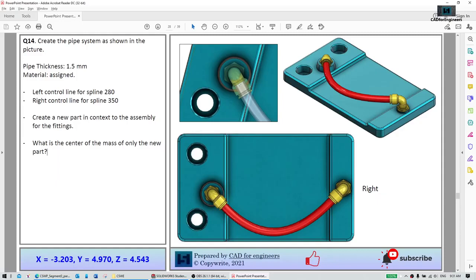First, just pay attention to the starting condition of this pipe. So over here we have a connection between this line. We will have a straight line, and we are going to use some tools like a spline. You just try to think about how you can create a pipe system like that. And you might think, let's try to create the profile using a spline tool, right? Then I'm going to create a circular profile cross section of the pipe. Then I'm going to use just the sweep command. That's it.